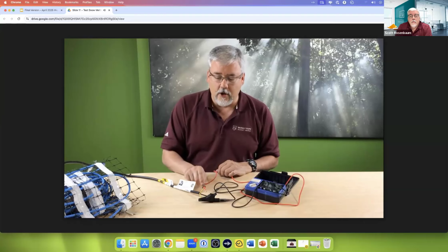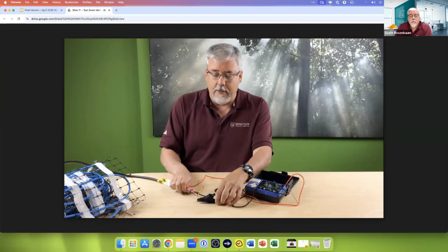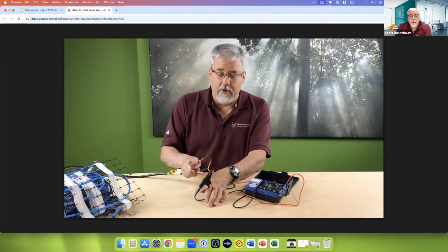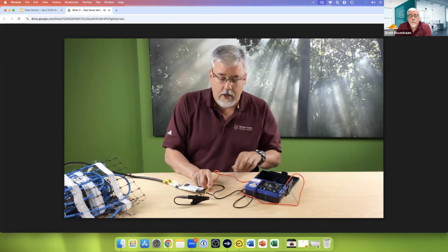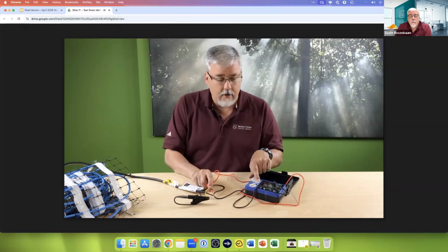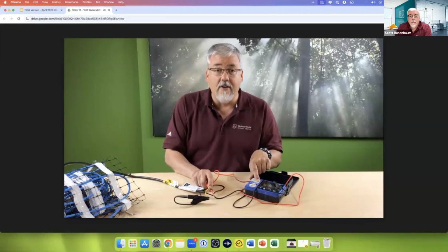The next thing I do is go from black, which you may not be able to see very well because it's behind the clamp. We'll try to do it that way for you. And we will then press and hold down the test button again. This is 500 volts.